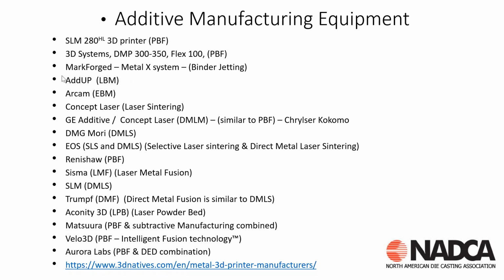Markforged is a company that is providing 3D printing, not only in metals, but in plastics and other thermoset materials. Their system for the metal is called the Metal X system, and that's a binder jet system. So that's a system that you're going to then have to wash and sinter the materials after they're printed. Then we've got AddUp, and those are laser beam melting, electron beam melting from Arcam.